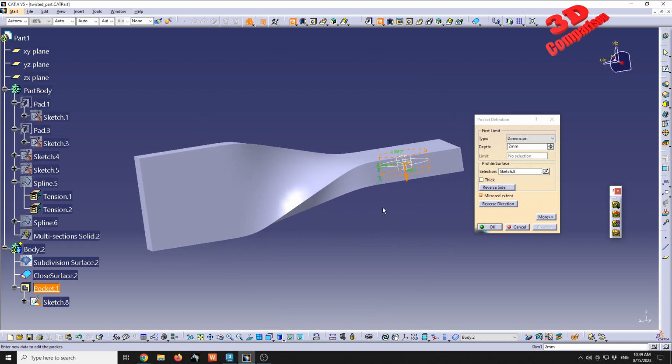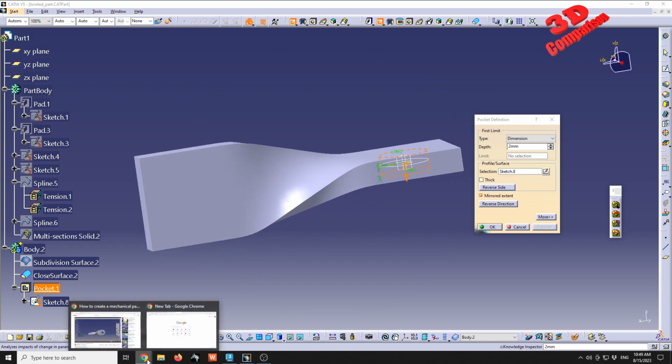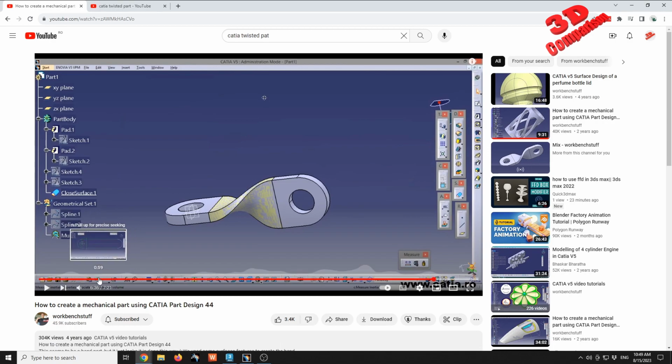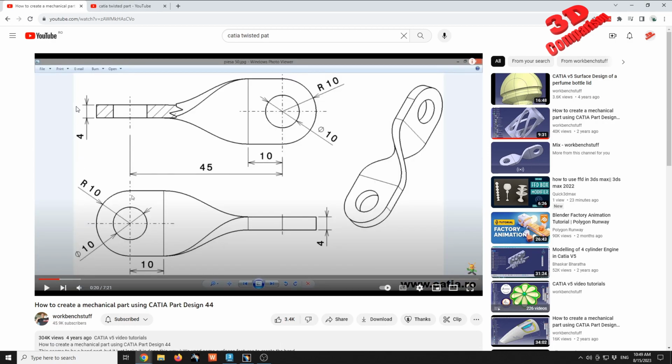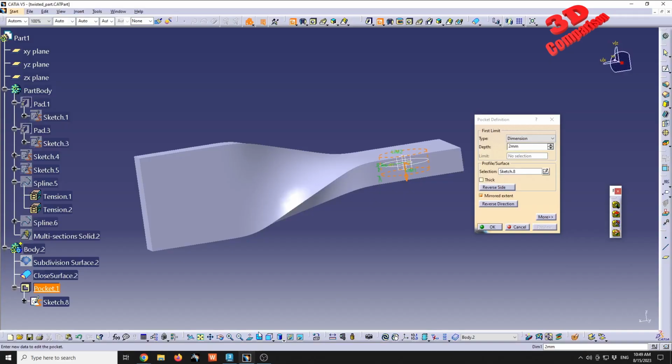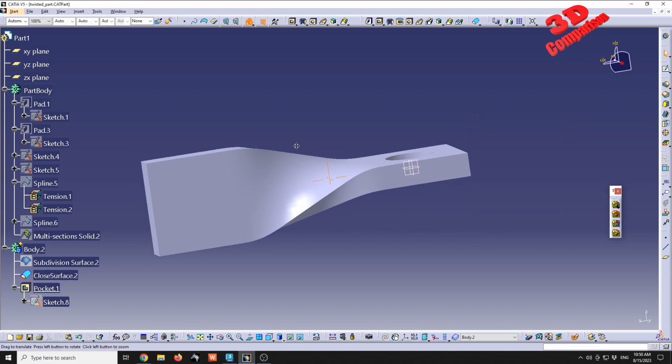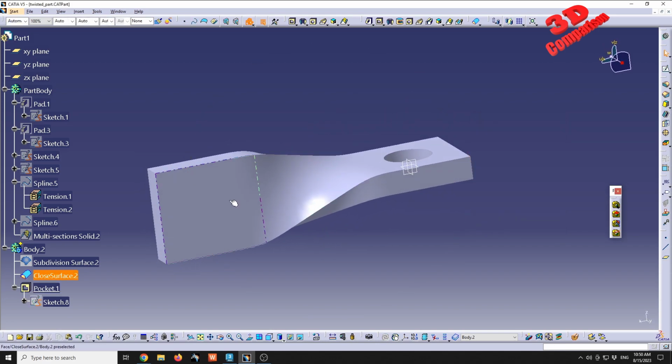Okay, so one of the differences, if I recall from that video, is that his initial design had only 4 over here. I made it within this part 5, so that's why it's not cutting through all. So I will just cut it by 2.5 to match this. We can do the same for the other side.